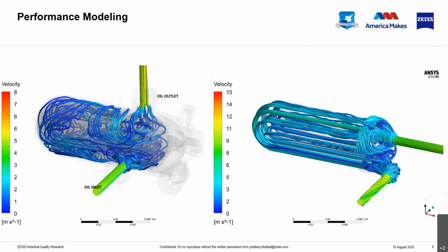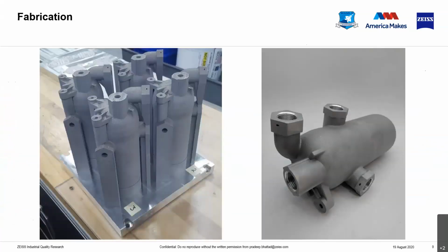And if you think about it, most of the functional surfaces are hidden inside the part, so they're not available for easy surface treatment procedures. Surface treatment sometimes can become expensive as well. So in order to understand this, we need to look at the defects and surface roughness as well. That was one of the key challenges going forward with this program, besides reproducibility. This part was created with aluminum, silicon, and magnesium, at UDRI in partnership with AFRL, I think on a Concept Laser machine.